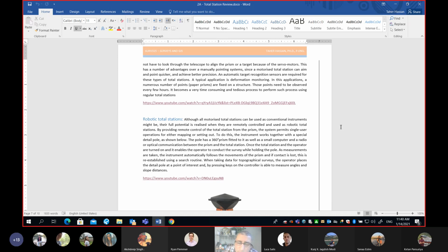So that's true. But did you notice in this video how many people were used for the operation of this special total station? Is it one or two? One. Only one person, and this person is simply the surveyor and the helper at the same time. I want to remind you the total station needs leveling and centering. So even though it's a robotic total station, very expensive, very complicated, you still need to level and center above one point. Please don't forget that.